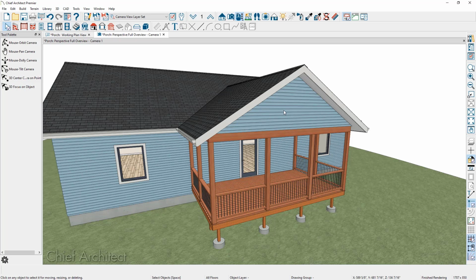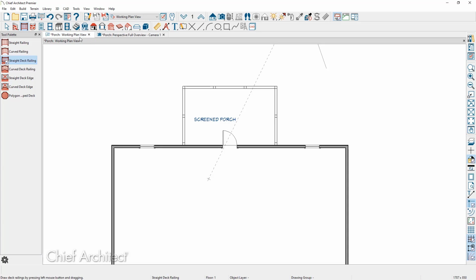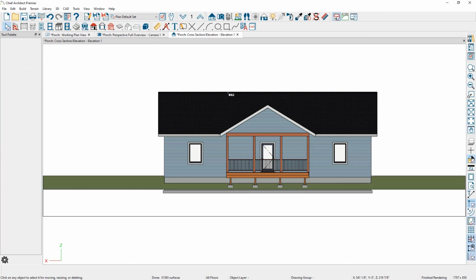For the next part of this video, let's go ahead and get the screen on all three sides of the railing. To do this, we're first going to get into an elevation view looking at the back railing, and then use the 3D Solid tool to add a 3D Solid over the area and change the 3D Solid to represent a screen. So let's go back to our floor plan view, and you'll notice how our room label changed to say Screened Porch there. Then we'll press spacebar, go up to our orthographic camera tools, select the cross-section elevation, and then just click and point it at our screen porch.